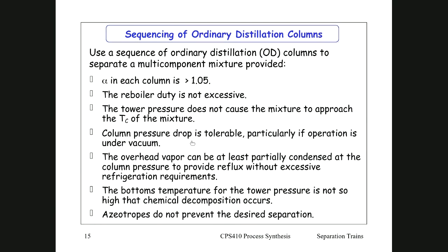And so generally, if you are going to be using vacuum distillation, you would prefer to have a packed column because then the vapors do not have to bubble through a head of liquid. They will simply be contacting on the surfaces of your packing.